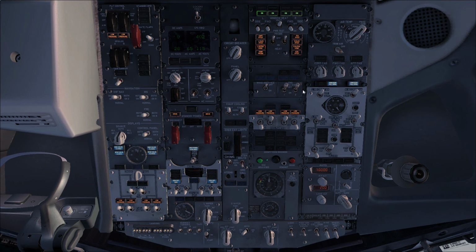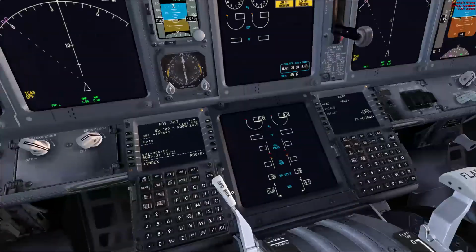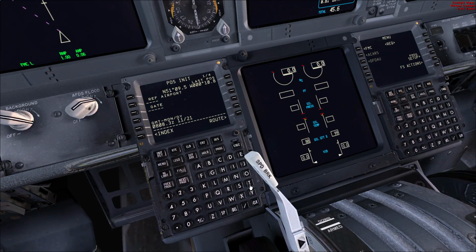Okay, I think we have ground air, so we're going to turn the recirc fans and left and right packs on. Ignition selector needs to go into the right position. This is where you'll go ahead, tune into the ATIS, get the ATIS, find out what runway's in use, do your takeoff calculations, put everything into the FMC as normal. So we're just going to do that quickly now.